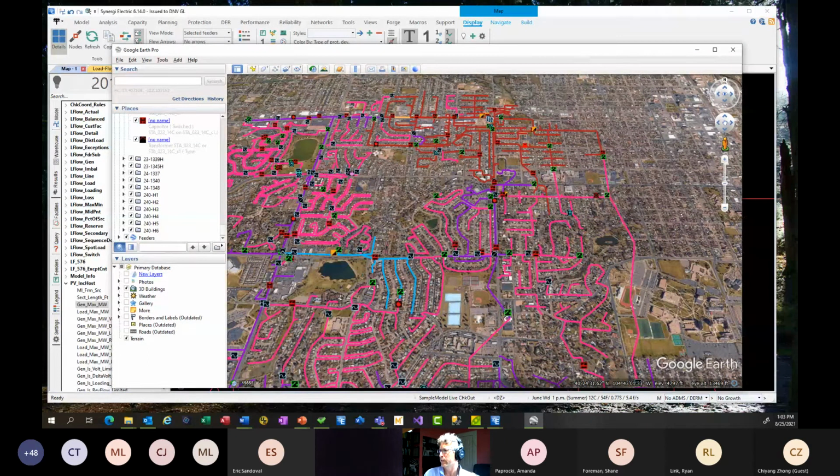The question on the secondaries, you don't have to have the secondaries mapped. You just need to have a way to associate customers and distribution transformers to sections. And so if that data can be pulled in, there doesn't need to be any geography on the secondary, it just has to be associated with sections. And then, yeah, the line thickness, you should be able to change the colors and line thickness in the display settings in there. Back when I was doing that tracing, you should be able to set those thicknesses up.